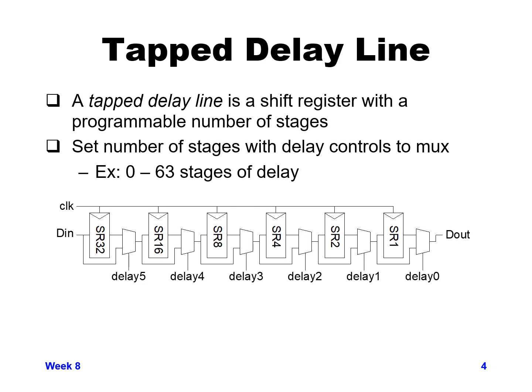Let's say you want to program the amount of time that it takes for the delay. In the previous example, we only had a delay of 4 because there was exactly 4 registers in series with each other. Down below, you can see an example of how you could have a programmable delay from 0 to 63 stages worth of delay.